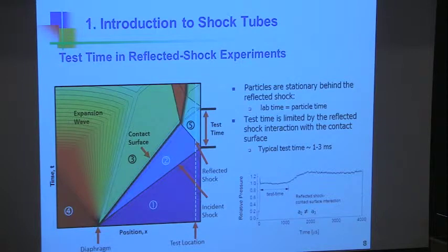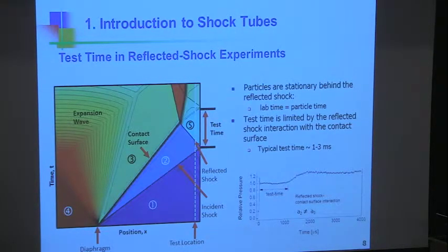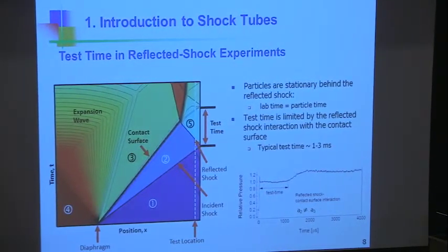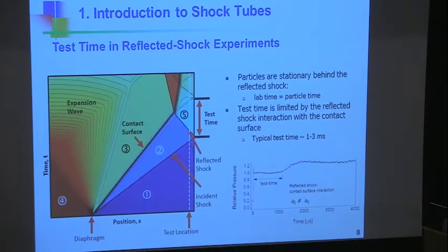Now, I guess I left out the equation of what Mach number can be produced. So you might have this question, well, what Mach number could I produce? The people who wanted to study Jupiter entry wanted to know, well, can I do it? Can I produce Mach 25 into that Jupiter atmosphere? And it turns out that you can't quite do it with room temperature driver gas, P4 over P1. You have to heat the driver.